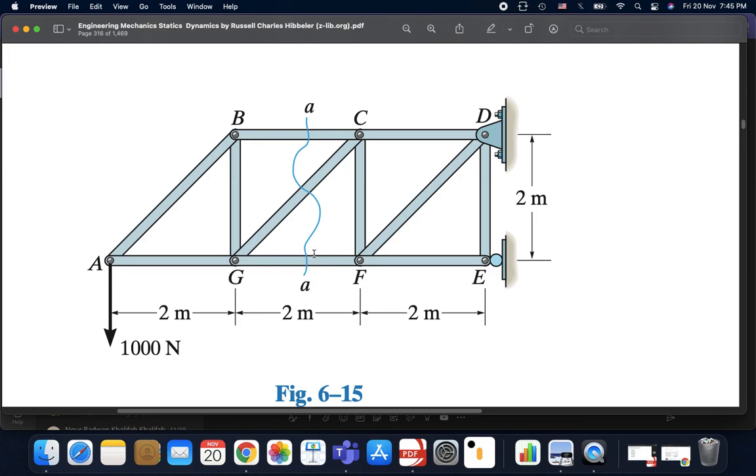So remember, you use 3 equations, and our golden equation in the method of sections is the moment equation. Why? We will discuss that later. Anyways, you take a section where you can have a maximum of 3 members, and then you start solving your problem.